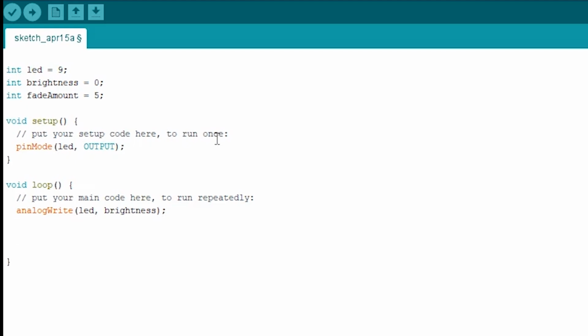And then next, what we need to do is change the brightness for the next time we go through the loop. Because every time it goes through this loop, it's going to assign the brightness to it. So if we use the loop to our advantage to change this variable every time we go through it, that's how we can effectively simulate the dimming and going back.